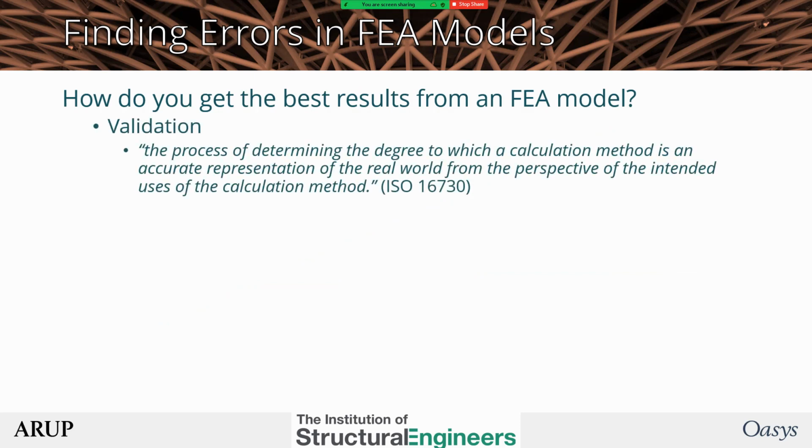There is validation. Validation is ensuring that the model is valid. Does it answer the right question in the right way? Is it realistic? Does it include important checks and details like voids or stability? Is the modeling appropriate? The Hartford Civic Center model was invalid because it ignored important details, such as the way as-built connections induced large amounts of torsion in members which had virtually no torsional capacity. Their analysis approach was also invalid as they did not check for torsional buckling. They did not ask the right questions.